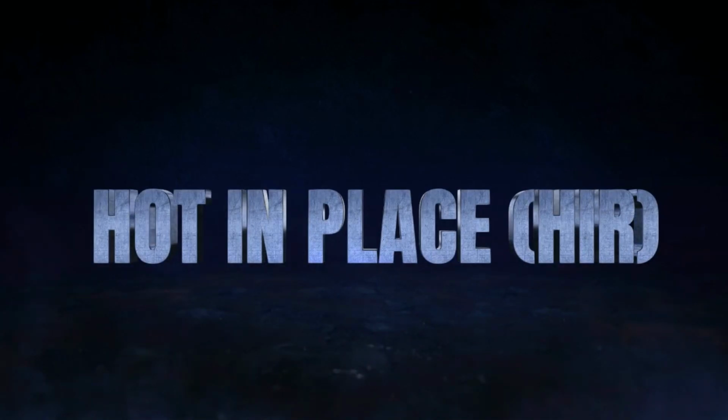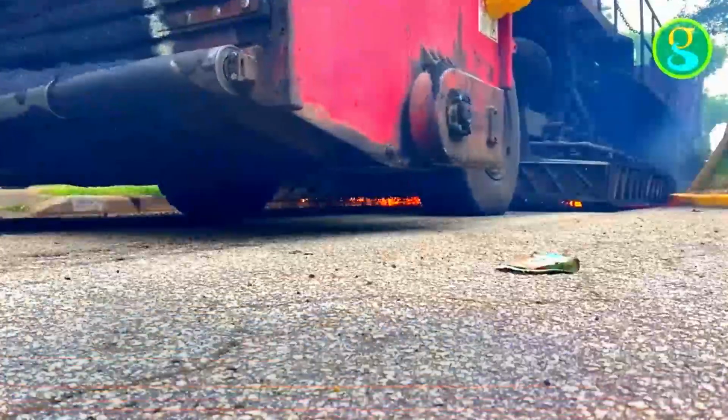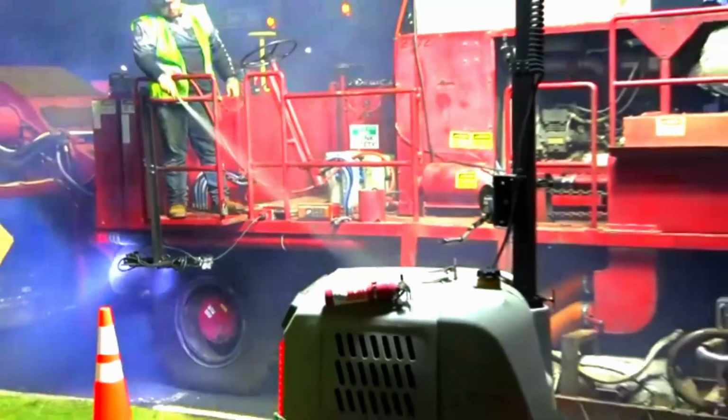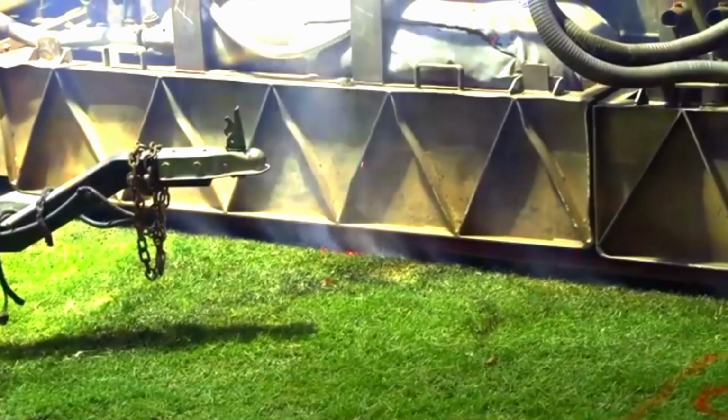HCPR process. Step 1. Heating the existing pavement. Specialized machines heat the existing asphalt surface to soften it. The heating depth typically ranges between 30 to 50 millimeters, depending on the pavement condition.